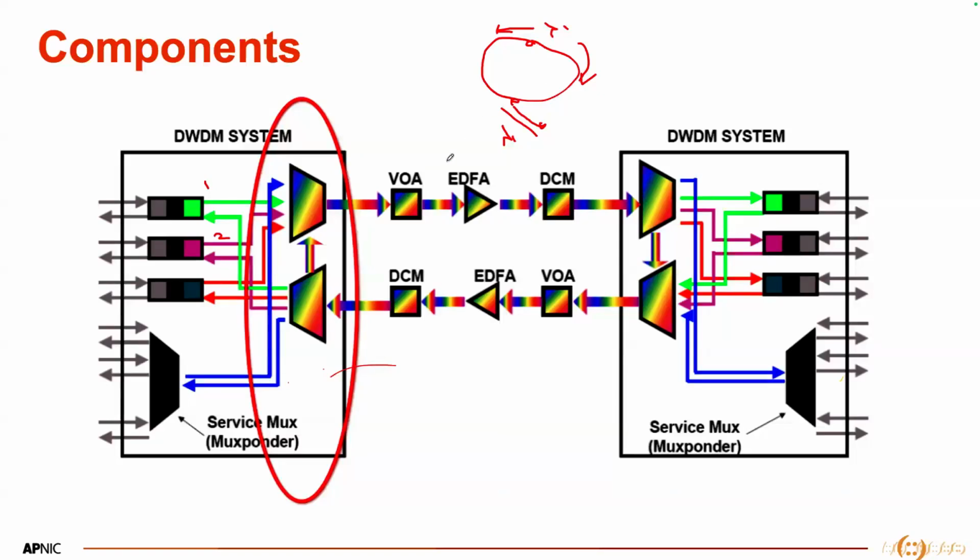So that is the idea of repeating lambda. You cannot basically repeat lambda in a DWDM system. That is the main concept. But for some exceptional requirement or exceptional design, you can actually do that if you are running out of wavelengths or lambdas.